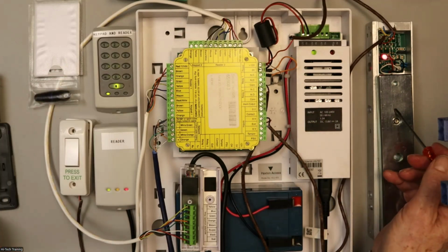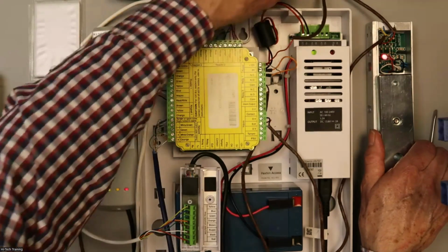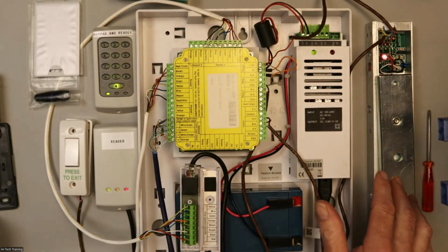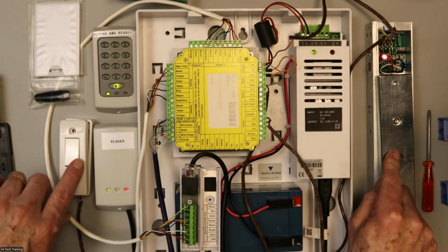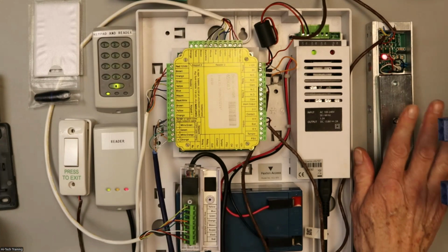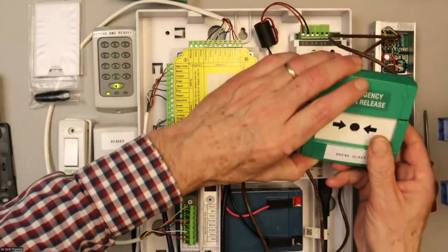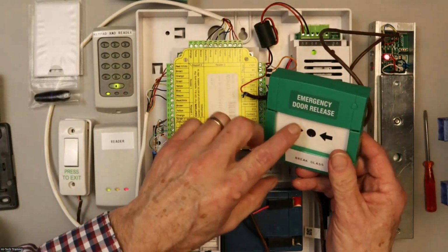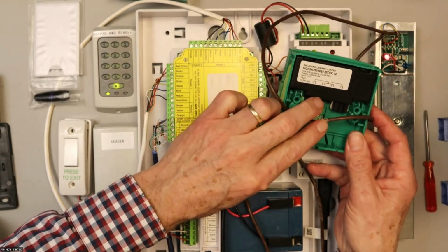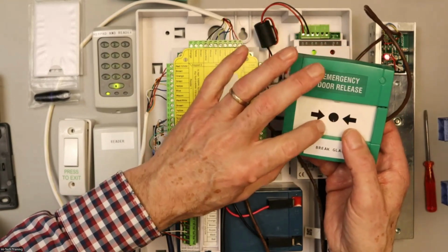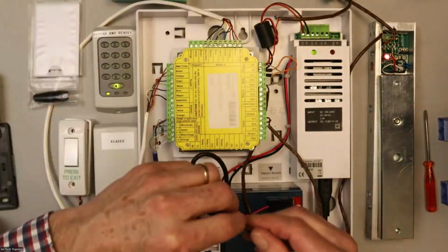Over here, you have your connection to the lock, and in series with the lock there. With this particular type of lock, you've got to assume, hopefully it'll never happen, that if all of this goes wrong and the lock stays on, my exit button for whatever reason doesn't work or my readers and keypads don't work, I need to take the power off of this to open the door in an emergency. To do that, I use a break glass unit here. This device is wired directly in series with the Maglock, right? So I've got my in and out here that I can actually break with this unit. We call it break glass, even though this particular one doesn't have plastic to break. It's a resettable device. Just reset it with this key here.